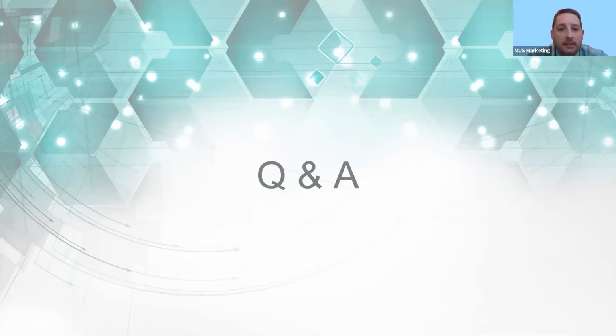Okay, great. Thanks, Rich. The next question is, you mentioned Modbus conversion. Do you have a Profinet to Profibus converter, and can you do Profibus to fiber? Todd, you want to take that one? Yeah, sure. We do the EMGate. It's the 5111, and there is the EMGate 5102 for Profinet to Profibus. And was the second question about Profibus to fiber? Yes, Profibus to fiber. Okay, that would be the ICF line, which is the 1280 and 1180 line.